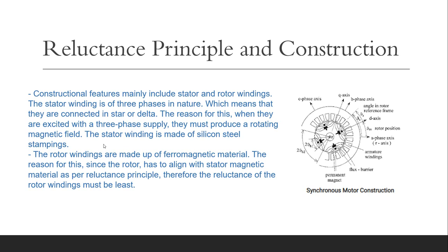And the rotor is made up of ferromagnetic material. The reason for this is that the rotor has to align with the stator magnetic field as per the reluctance principle, therefore the reluctance of the rotor must be least.